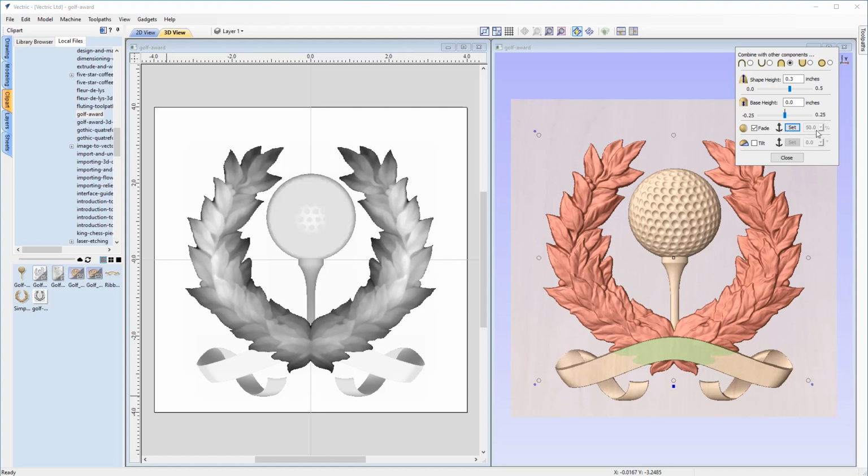So if we just go ahead and set those two anchor points, we'll left mouse click here to set one, and one down here as well. And that just sets the direction of the fade. And you'll see that by default it's set to 50% on the fade. So you can see that at the top here, the details still remained unchanged. But as you get closer to the bottom, for the second anchor point, it starts to fade out. So some of that detail is getting lost.